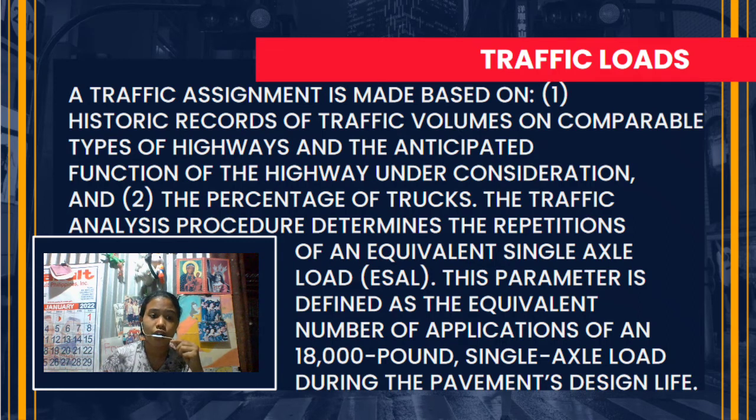The most common approach is to convert axle configurations and axle loads of various magnitudes and repetitions, or what we call mixed traffic, to an equivalent number of standard or equivalent loads. The most commonly used equivalent load in the US is 18,000 lb. Equivalent single axle loads are normally designated ESAL. This is the loading format used in FPS 21.